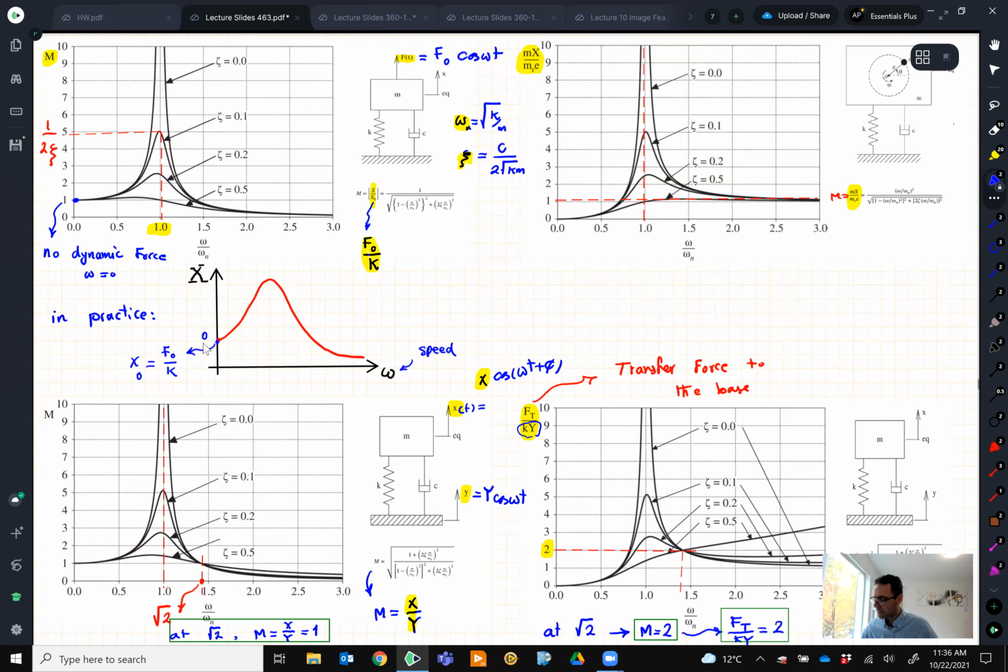And then they increase the speed or the omega, and they get a new value for x. They repeat the test, and at some point, they realize the system gets crazy, and they know this is where omega roughly is equal to omega n. And this is when they quickly find out what their natural frequency is for this system.